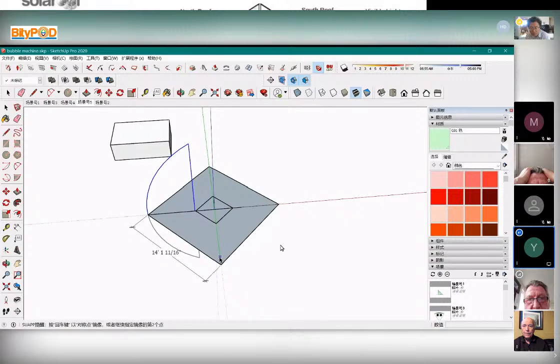And so that's where we would have a door, right? We could walk into this. The doorway is 3 foot wide. So we've got a 4 foot wide central workspace, and we're going to have a walkway. Let's just make the whole walkway 4 foot wide, so 2 foot each side, 2 from the center.